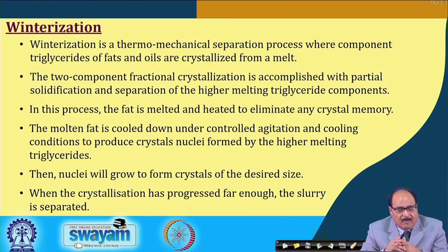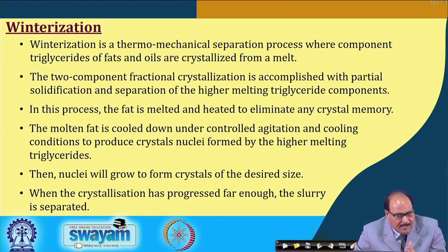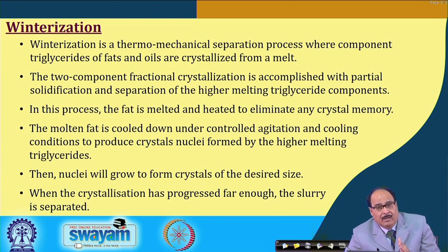In this process, the fat is melted and heated to eliminate any crystal memory. The molten fat is cooled down under controlled agitation and cooling conditions to produce crystal nuclei formed by the higher melting triglyceride, and then the nuclei will grow to form crystals of the desired size.